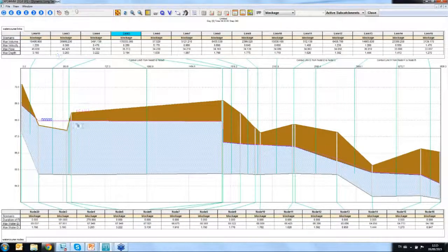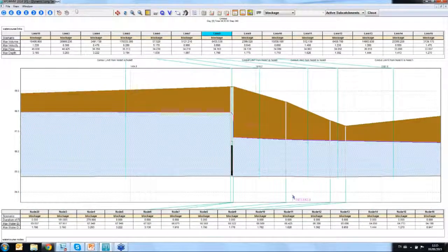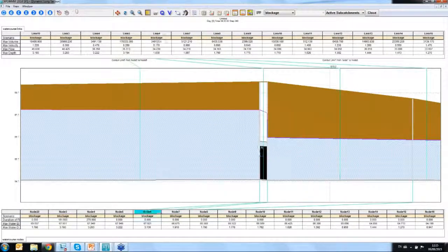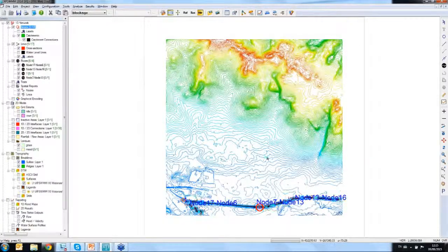And it's not as bad as it was with one diameter of a culvert, but we still are experiencing some upstream flooding. And if I zoom in to my culvert location, you can actually see that there is a blockage within the pipe. So this is a very quick way to analyze 1D elements of your natural watercourse.